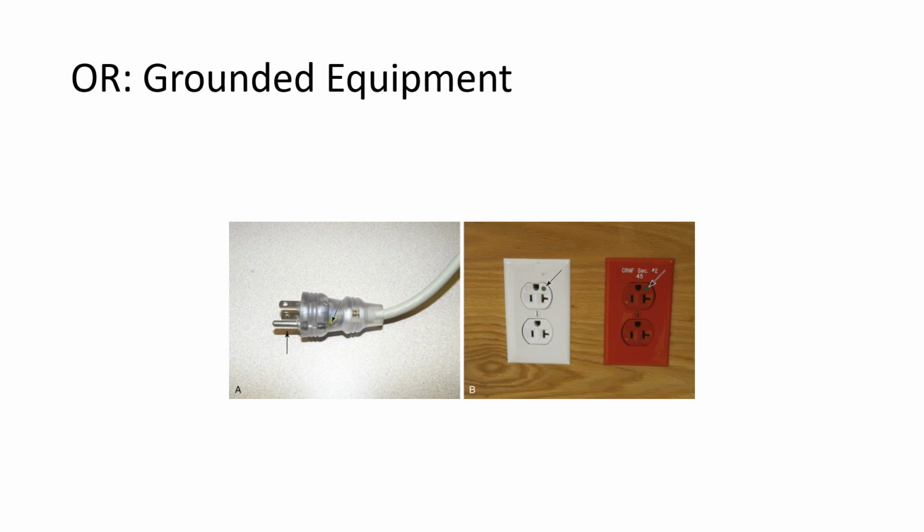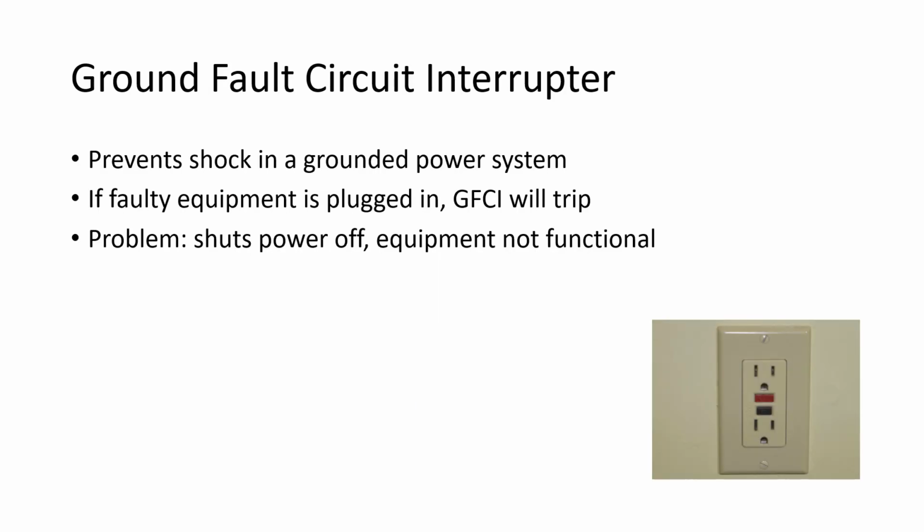Thus, if you have a broken wire or plug, that's a potential for danger. That's why hospital-grade plugs are supposed to be easy to inspect, like this, clear or easy to disassemble so they can be inspected. And these hospital plugs over here show you, again, that the ground wire should always be intact and is the one that should be inserted first into the electrical outlet.